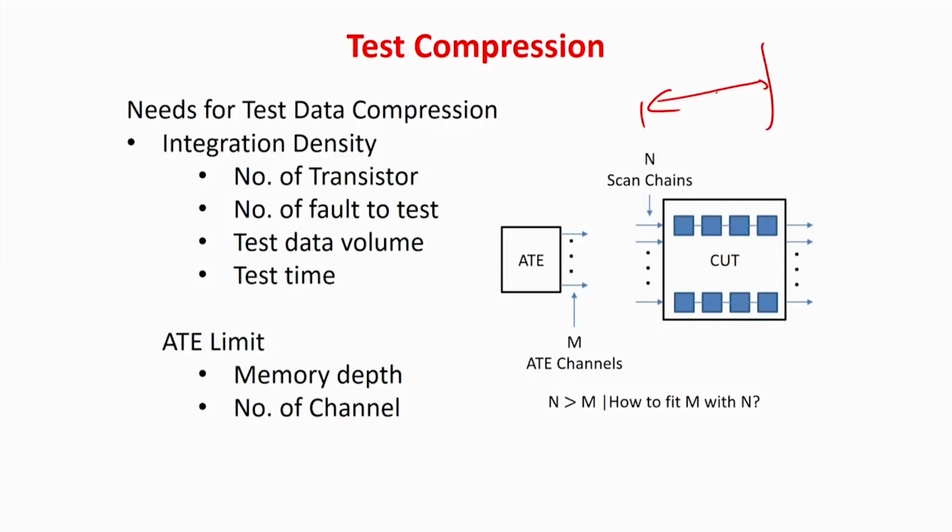Say, for example, I have 100 faults. An ATPG algorithm will give you some 20 patterns or 10 patterns which will be able to cover all the faults, and there are algorithms which give you the minimal number of patterns to do that. If you reduce it further, you may lose coverage. So compaction in this manner, reducing the number of test patterns, is a different problem from test compression, which we are trying to do today. Reducing the number of test patterns means you have to find the minimal set which can cover all the modeled faults. That comes under automatic test pattern generation and is a well-studied area. But today we are talking about compression.